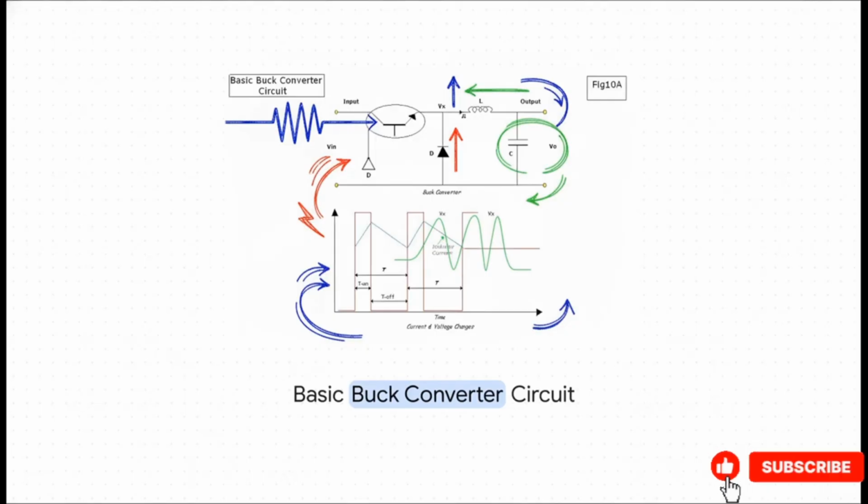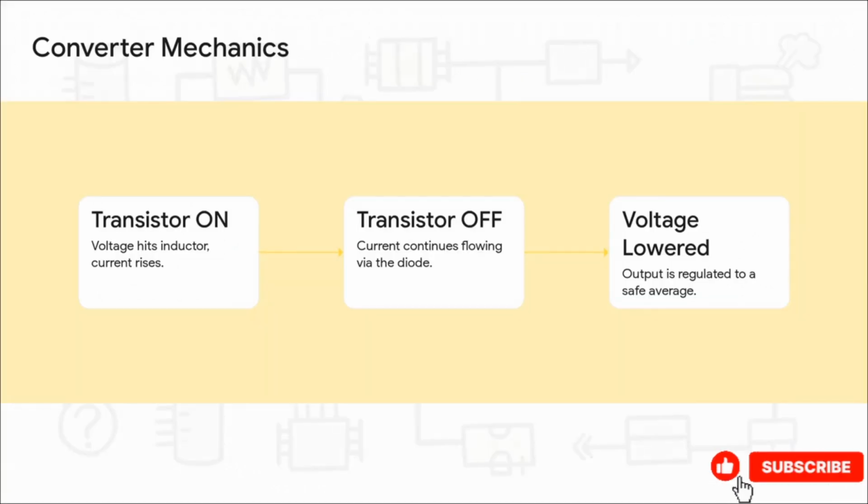Managing this pulsing current physically relies heavily on a few things: a transistor switch, a diode, and an inductor. They all work together to smooth out that rapid PWM pulsing into a nice, steady, clean output voltage. I mean, the rapid on and off switching would be totally chaotic on its own, so these components really act as an essential buffering system. Let's walk step by step through these ingenious mechanics.